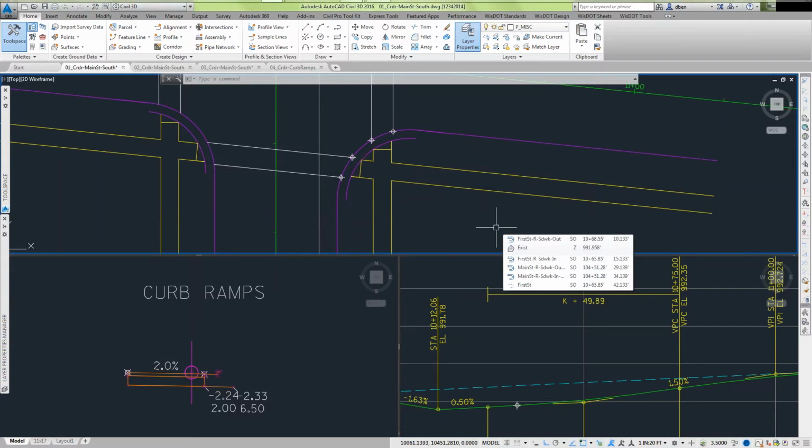All right, now design checks. According to the FDM 11-46-10.1.1, for side roads, the roadway longitudinal slope or cross slope is to be no more than 1.5%, and it needs to extend beyond the stop bar or yield bar, whichever is greater. For mainline roads, they may have a cross slope equal to the profile slope.